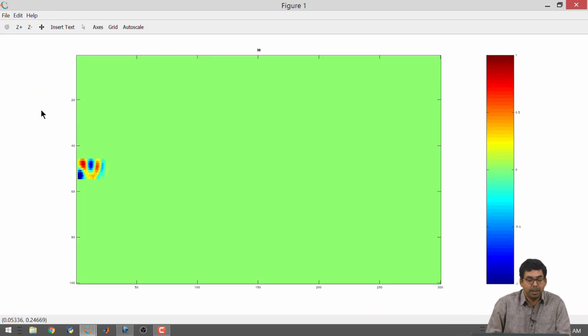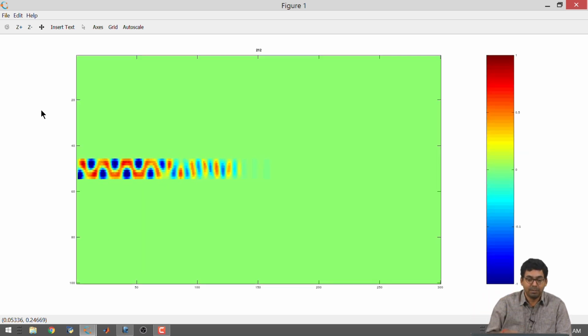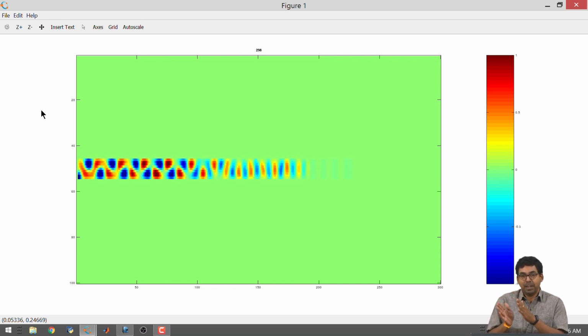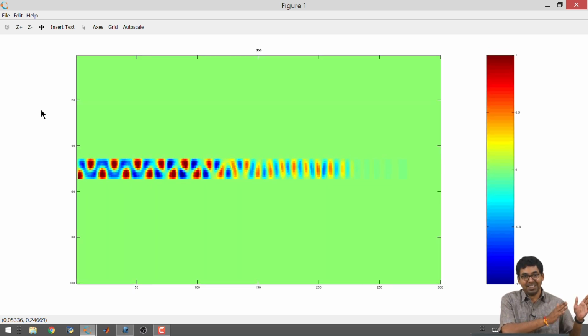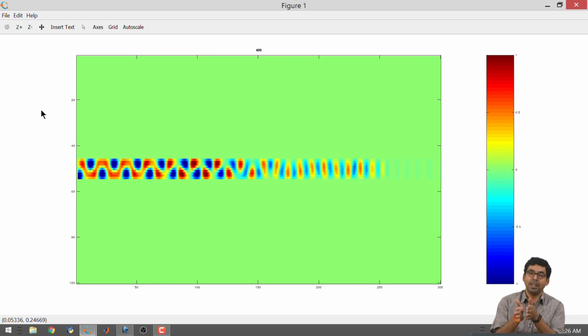Alright, now I get some propagation. But now there is an issue. Sin n by 2 means that you increase the frequency, but the adjustments you made to the width of the waveguide were valid for the frequency you were using before. Now again, for this operating frequency and this separation, how many modes are supported has to be recalculated.